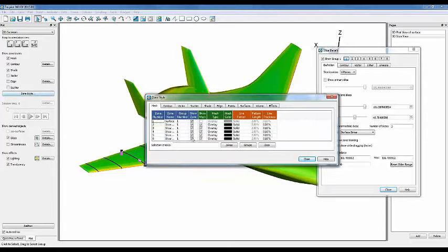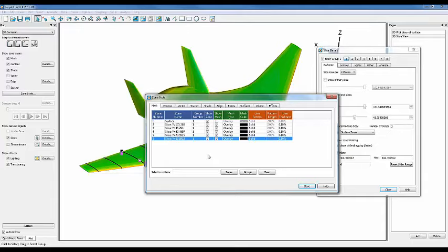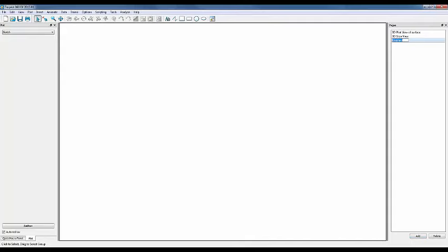If I go to design styles now, you'll see that we have slices from y equal 101 nominally to about 60. So now that we have those slices available, we're going to come in, add another page, and we'll call this CP plots. Okay. Now these are going to be non-normalized. We do have a macro available that will come with the data that will normalize CP so that they all start at x equals 0 since it's a swept wing. Not going to worry about that right now.